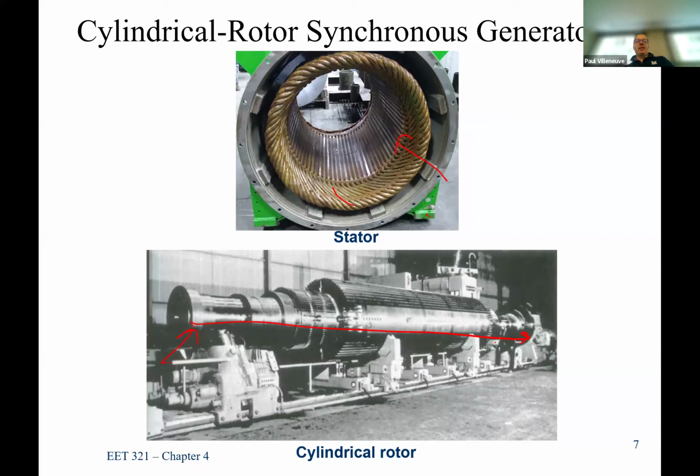But if you remember, the shaft size of those things are monsters. A shaft size like this could be good for 300 MVA, but if you spin it at 3,600 RPM, that same shaft size could do 2,000 megawatts. So it just would be a lighter one for a much bigger application. And then again, you need that long length, so it's got to be standing up. Now you have to erect something that goes straight up and won't move around. So we have to build this, it has to be practical, so it makes it challenging.